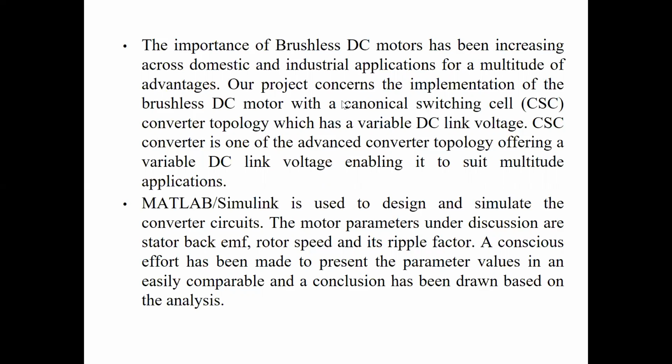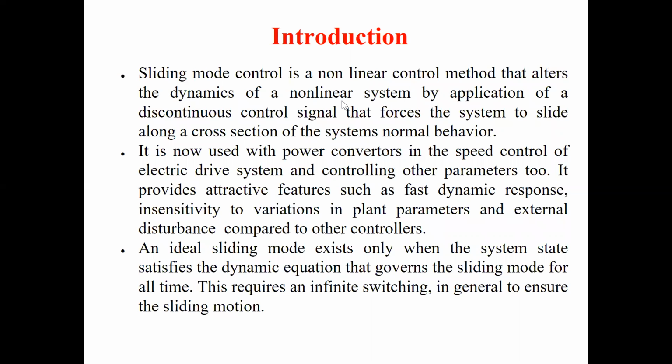Moreover, first, to analyze whether this is suitable or whether this will work out, we just did a Simulink model. With all the parameters of the brushless DC motor, we simulated the entire model and checked whether it is capable of giving the desired performance. We say that in that approach we got success, and hence we went for a prototype, and we felt that the prototype is also working well. It gives a very similar performance to the Simulink model.